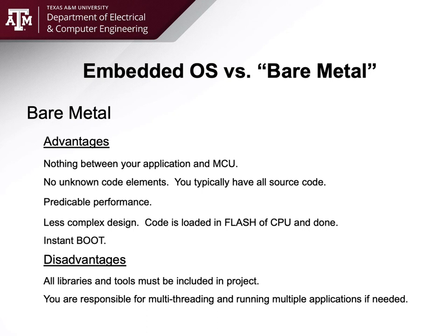So you can create a U-boot, and since that's the instant boot part, if there's some specific hardware functions that need to be done on boot, you can do it there while the kernel is loading. It usually takes several seconds for the Linux kernel to load, somewhere in the neighborhood of 2 to 6 seconds for the kernel to completely boot. So that's good, U-boot takes care of some of the basic I/O.